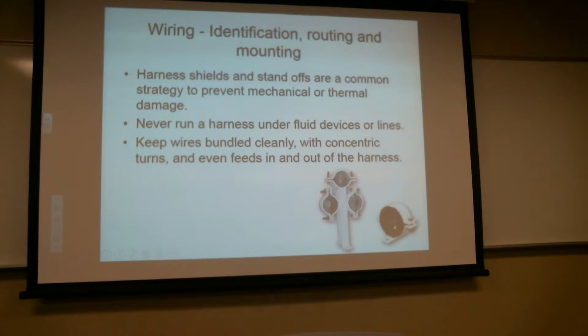I think to do the job well, you need to make nice concentric, symmetric turns and routing so that it looks relatively sanitary, and something that's been damaged or in other ways mechanically affected becomes obvious. I've got nine wires that play out real nicely, and one of them looks all kind of funky and doesn't look right. Well, it's because the connector broke or came loose. Now it's dangling, but it stands out. It's real obvious to you, to the eye. Your eye finds it quickly.